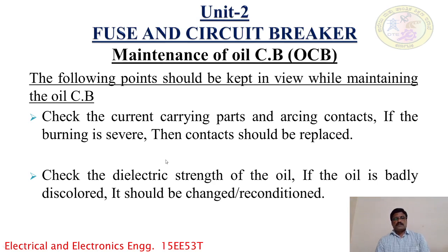Hence, check the dielectric strength of the oil. If the oil is badly discolored, it has lost its dielectric strength, and it should be changed or reconditioned.